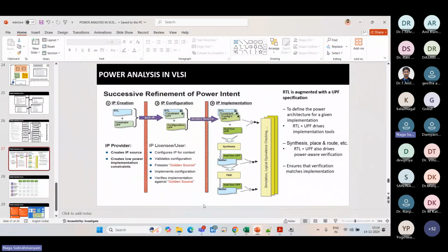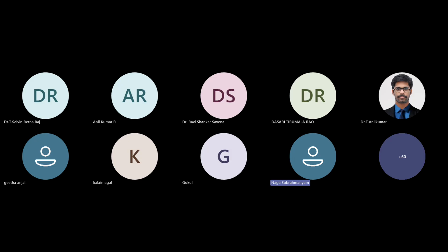And there are some places where we can estimate the power by using a tool. Suppose you see the Xilinx tool, it has a power estimation tool. After your logic design, it will give you some power details on how much power it will require.